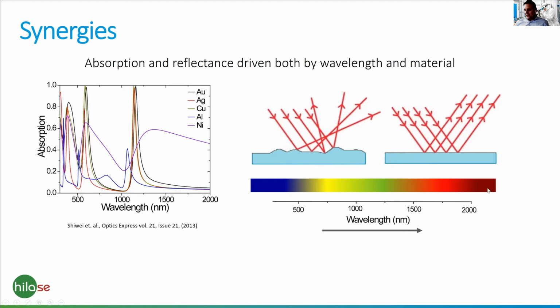However, when you are increasing the wavelength and going to the longer wavelength, then the surface from the light point of view can be seen as completely flat and basically act as a mirror. This often happens when you are using, for example, a CO2 laser at wavelength 10 microns. So even a surface which you consider in the visible spectrum as quite rough acts as a very good reflector